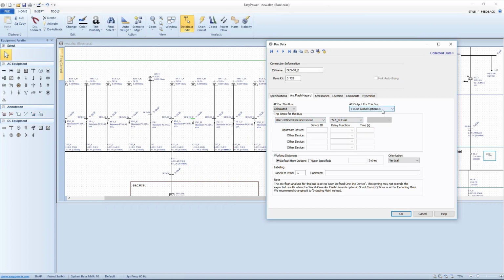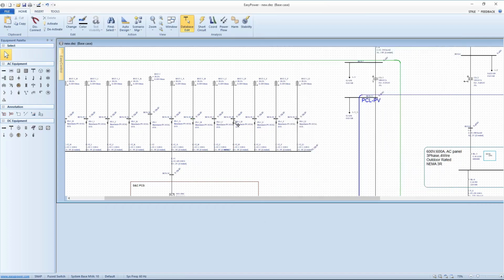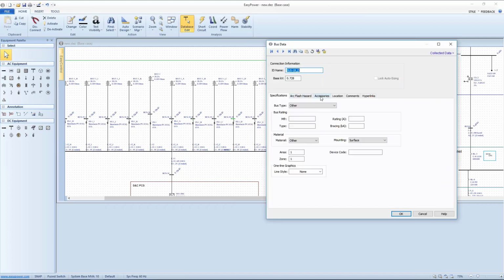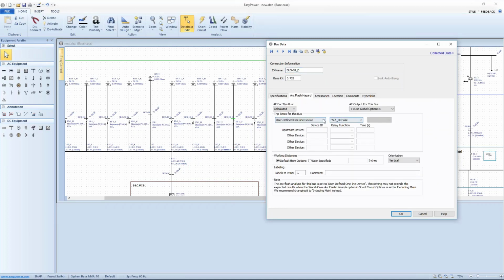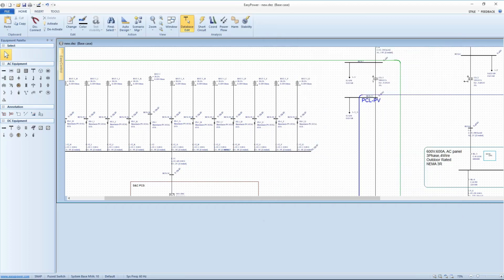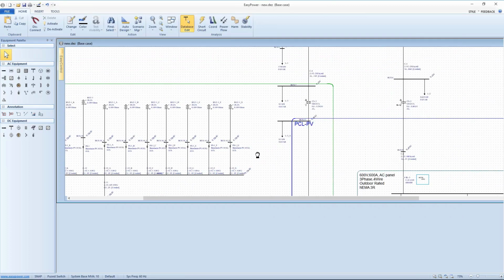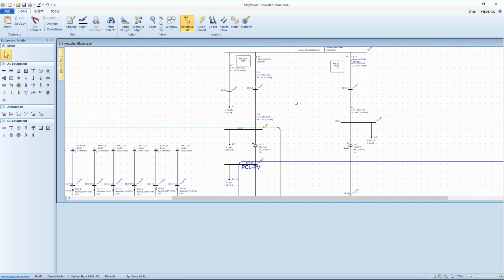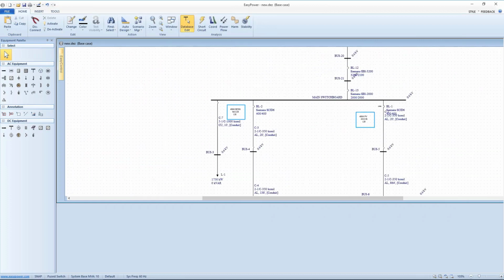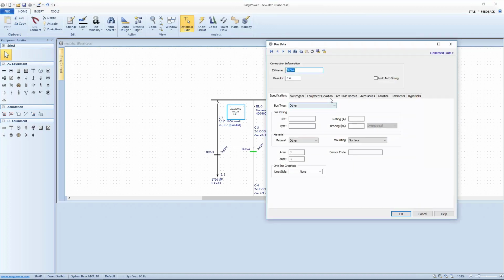And in this case we're using the global options for the rest of the settings. So each of these buses now is going to have designated arc flash protection by that next upstream fuse. So that's unique and hasn't been a feature in EasyPower prior to the last update in 9.8. If we come back to this bus, which will be again upstream,